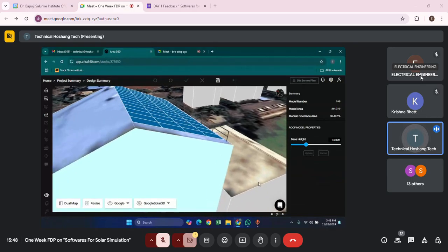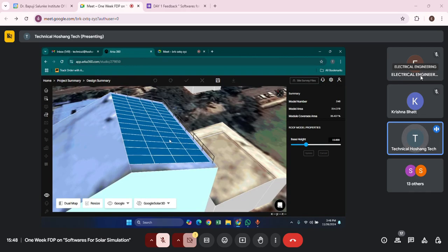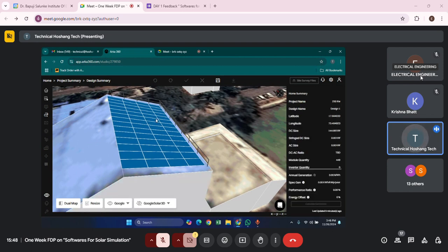The next thing we need is roof access. We can have it from any other side, or we can have it temporarily directly from this side, and you can lift all the solar panels. There's one thing you have to keep in mind, all the parameters, while installation. Each panel weighs 35 to 45 kgs, so you have to lift and place the panels properly. These things you have to keep in mind. While designing, let us now move towards panel design and table.